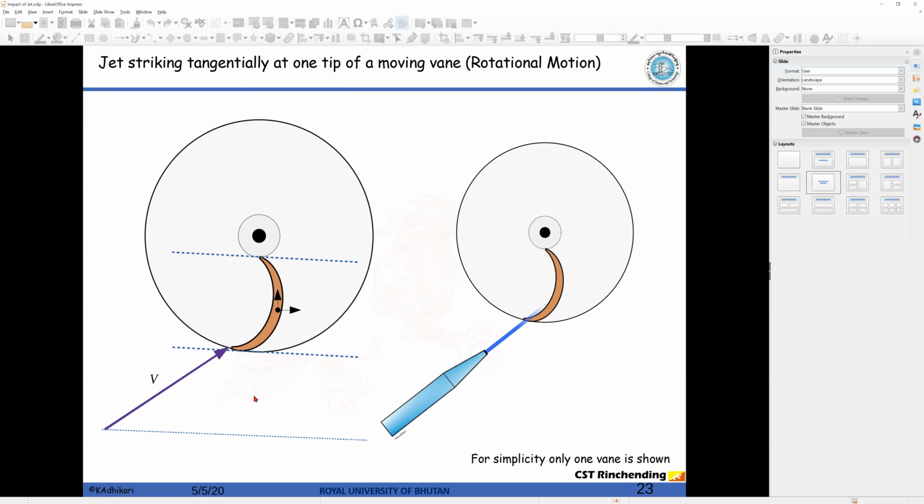Likewise, quickly let's construct our velocity triangle. This is our velocity triangle at inlet. Everything remains the same. That is our velocity triangle at outlet. Understand here that V1 makes an acute angle with U1. In the previous case, I intentionally made it obtuse to make you understand how the analysis would change if it is obtuse. Here it is an acute angle. This is the velocity triangle at inlet and outlet. It remains whatever I explained in the previous video.